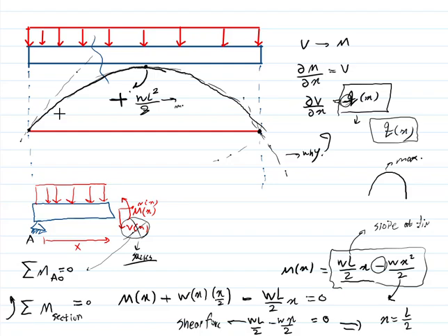Because if you pass the concrete course, you understand when you have a negative, you put the bars on the upper fibers. We call them negatives, and it will be here. So they say, okay, let's draw diagrams in a way that shows the position of the tension bars. So sometimes we try to draw the bending moments like this and call this positive. And for that, you have to say Qx. So that's the only reason, and it's not important at all.